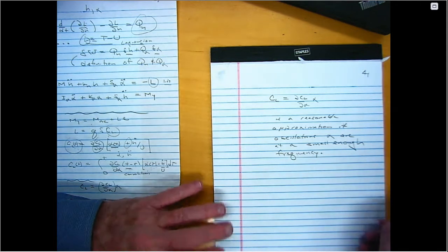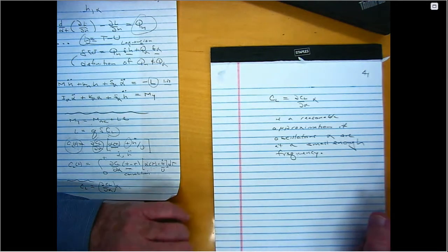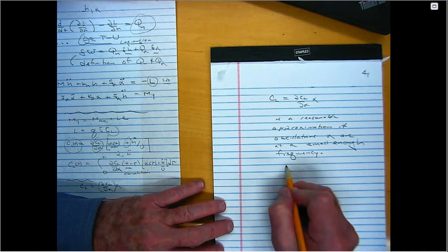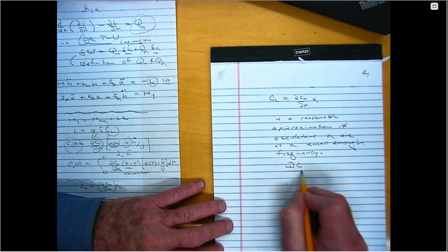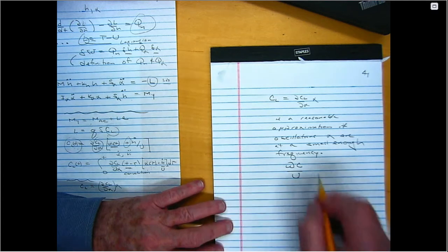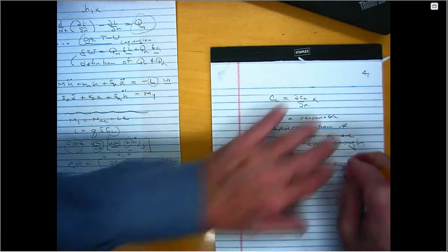What does that mean? Does that mean 1 hertz? 0.01 hertz? Well, again, you have to think non-dimensionally, because that's the way the theory suggests you should think, and that's the way experiments also suggest you think. It's really the frequency times some characteristic length, which could be the chord, for example, divided by the flow speed. This is known as the reduced frequency. It's really a non-dimensional frequency.